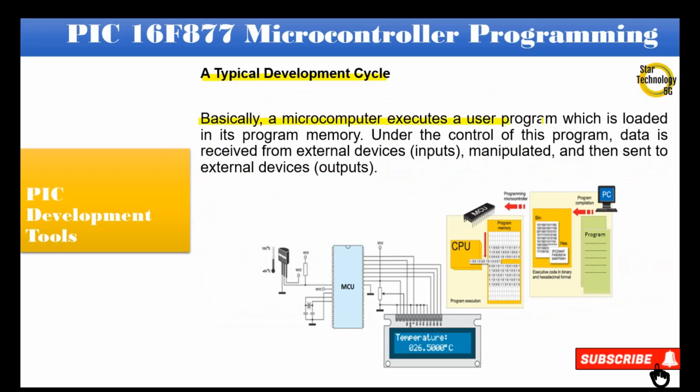A typical development cycle. Basically, a microcomputer executes a user program which is loaded in its program memory. Under the control of this program, data is received from external devices, inputs, manipulated, and then sent to external devices, outputs. You can see in the following diagram. A program written on a PC is converted into machine language code and then burned into the microcontroller. Then the microcontroller executes the program and shows the temperature on the LCD.